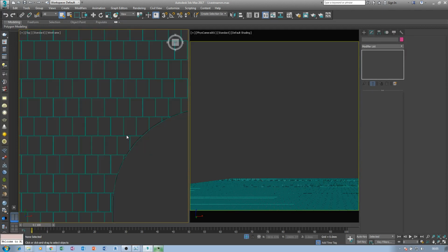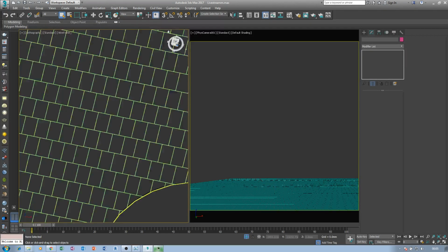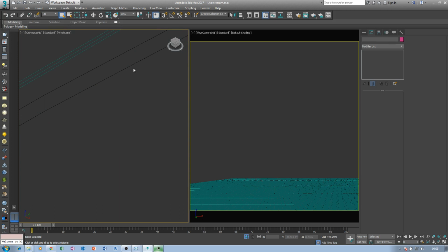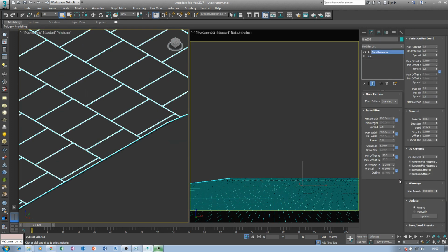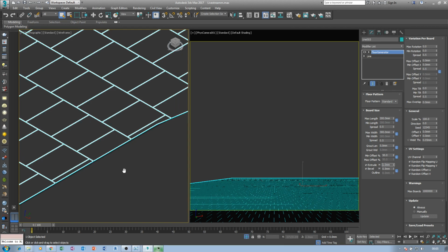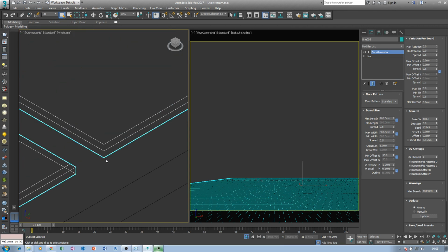And normally we don't have any problem because we have a base, a floor that I brought from Revit actually as the base, and that's the way it actually works in real life. Then I pick this as well. You see extrude now is 1 millimeter thick, so I'm going to change it to like 20 millimeters.